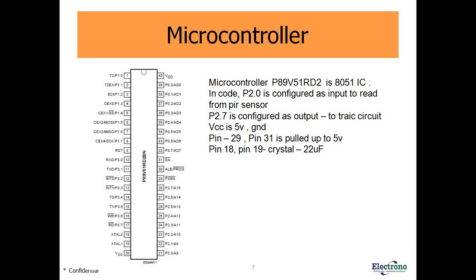So the crystal oscillator frequency is still less compared to 8051, but the prescaler value is also reduced. So my controller will actually get around 4 megahertz. And if we consider AVR, they have a prescaler of 1.